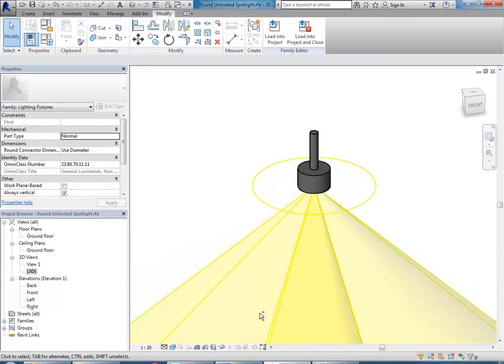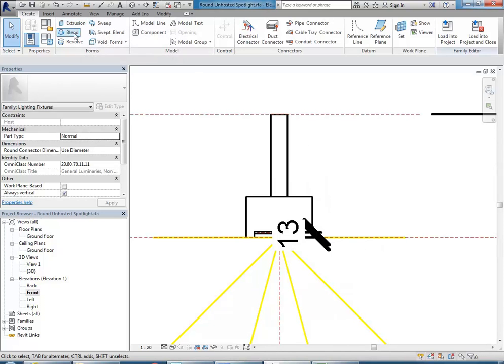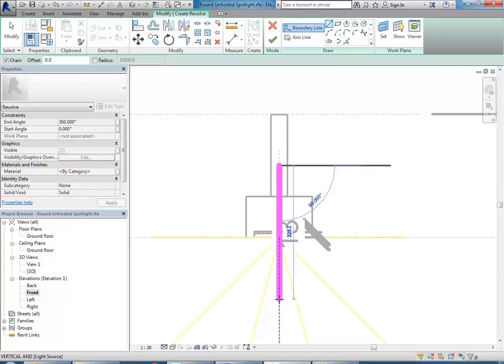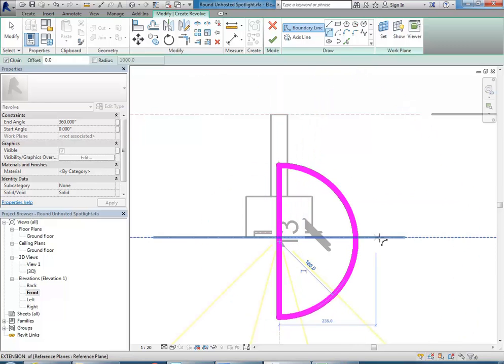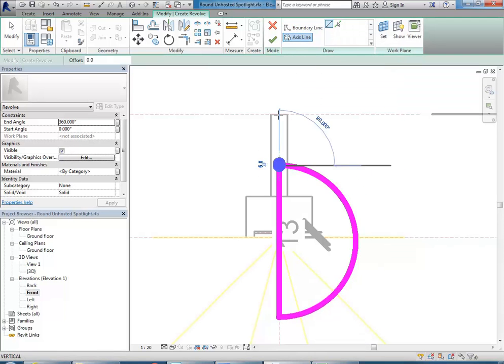Just make a revolve. So yeah, sure. If you want a sphere, are you making it in section? Yeah. Okay. So if you do go to revolve here, we'll draw a line actually to begin with, and then an arc, and make a semicircle. Because it's going to revolve around, and if you revolve a circle around, it'll go over the top of itself. So it needs to be a semicircle, and then draw an axis line in line with that inner edge.